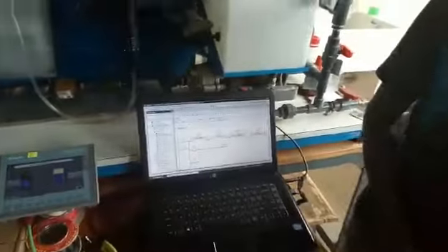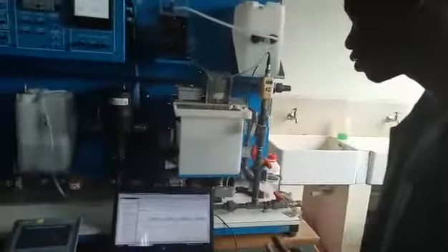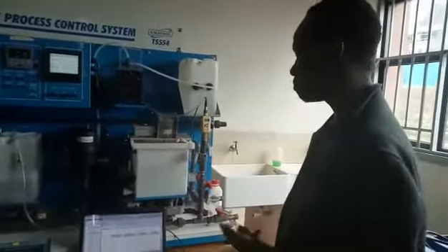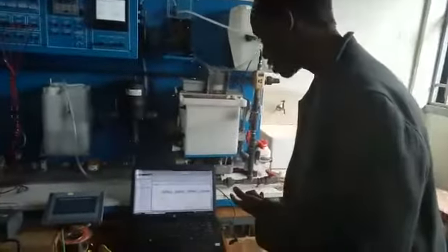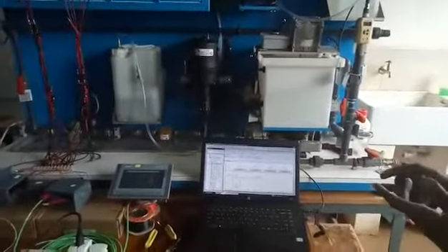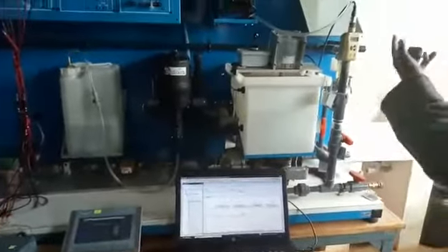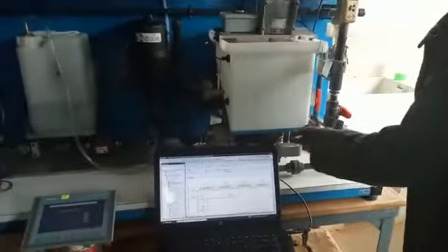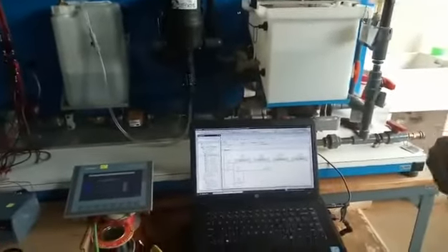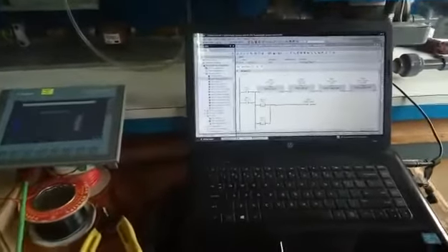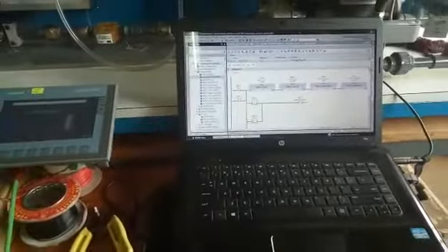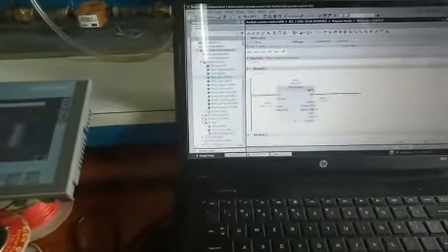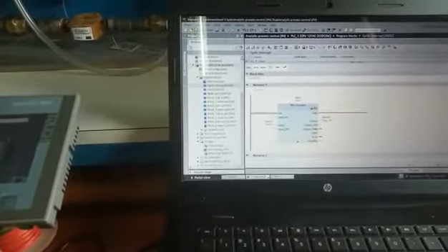Joe, please. Thank you. As my teammate has said, I am taking you through the program. Basically, in our program, we have 2 cyclic interrupts, 4 function blocks, and one main organization block. In the cyclic interrupt, what we do is collect the readings from the Honeywell pH sensor and the pressure sensor with the PID to get the desirable output to control both the flow control valve and the metering pump, as you can see in the program, for the water PID and for the pH PID.